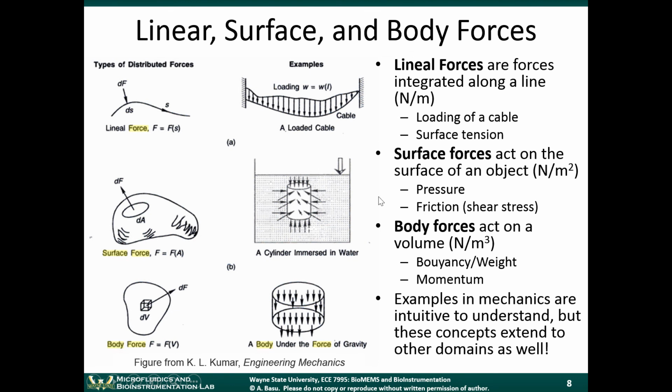So examples of surface forces: pressure is one of them, and friction is another one. When I'm taking my hand and rubbing it against this thing, the more surface area my hand has, the more friction there's going to be, right? One of the very detrimental things that happens at the microscale, if you're trying to make objects that move, is that surface area is significant at the microscale. So anything that's negated by friction, you're going to have problems with that. Friction starts to become very significant at the microscale.